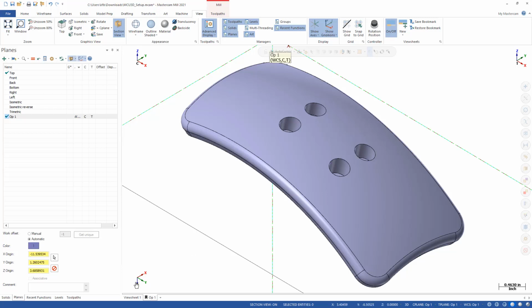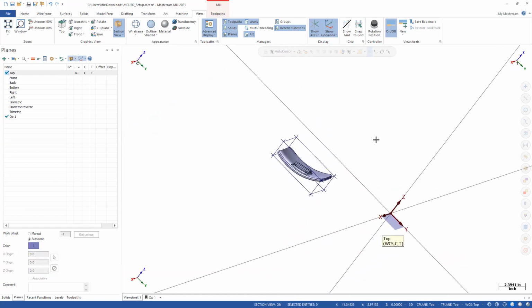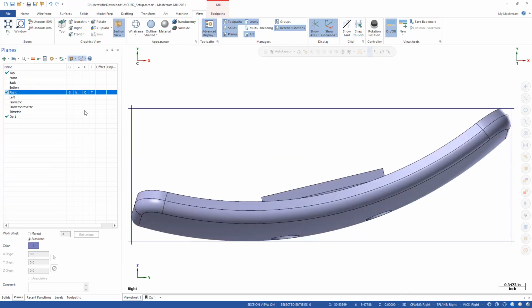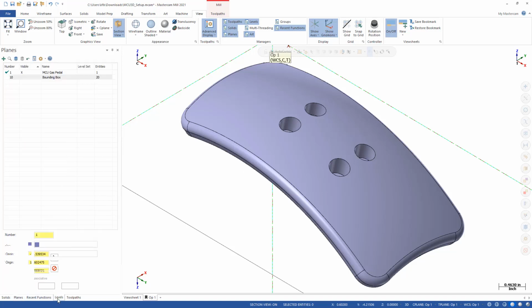And to prove it, if I go back to View Sheet 1 by simply clicking on it, positioning it in any way I want, setting any plane to be the active plane, if I go back and I click on Operation 1, the orientation updates, the plane updates, and whatever levels were on or off automatically get reset, and that bounding box is off and level 1 is on.